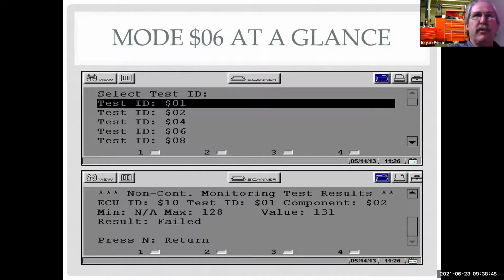Normally, with very few exceptions, you either get a 420 or a 421. You don't get both options on a vehicle, so they're either monitoring the warm-up cat or they're calling the warm-up cat their main cat. So it gets into a numbering thing. Very few cars, Volkswagen's one of them, actually monitor the warm-up cat and the main cat separately, and that's only on a couple models.